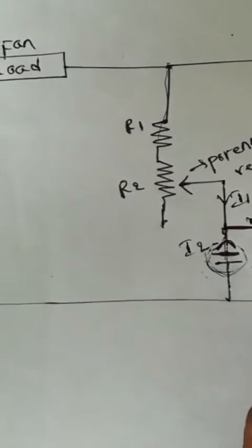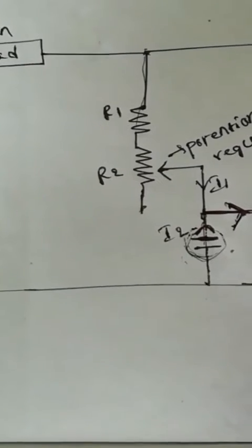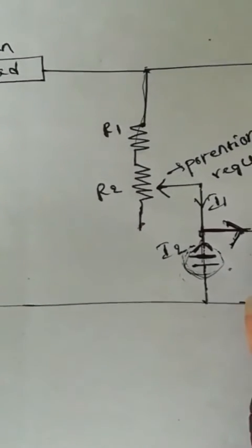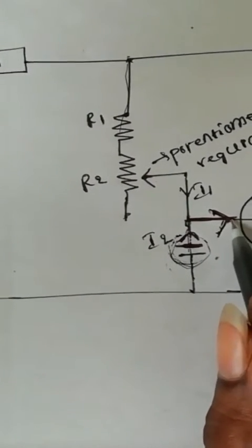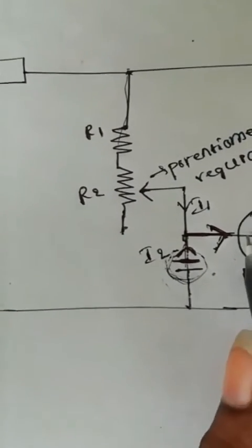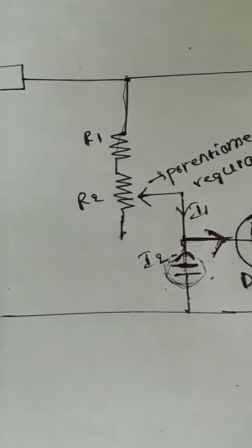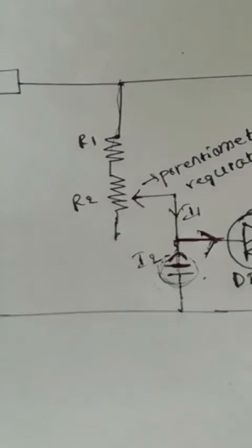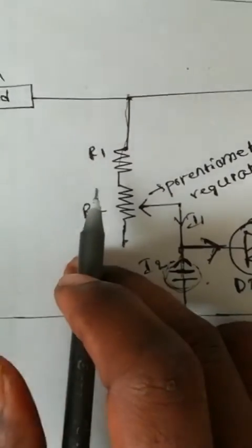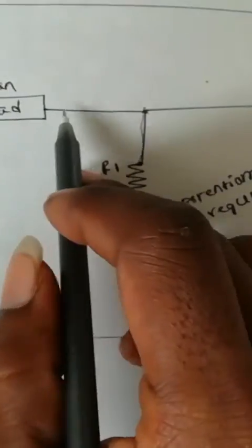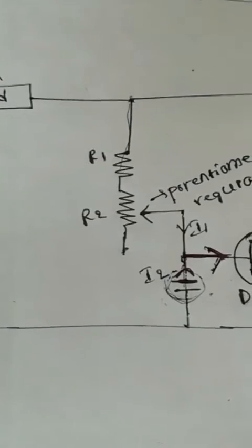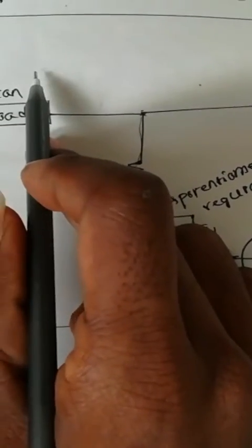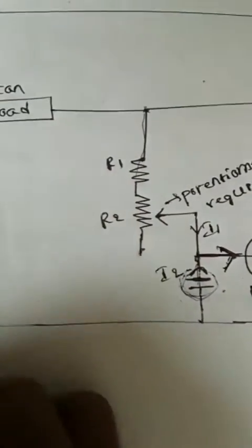So they will be able to activate our diac component, and after activating it, it acts as a short circuit. So the current flows this side and through the gate terminal and activates the triac component, and it acts as a short circuit. In that case, the maximum amount of current flows this side, so our load is directly connected to our 220 volts AC supply.